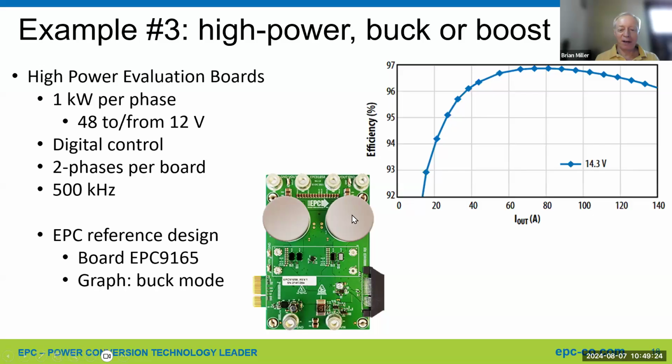But another point is the inductors. You might think, well, inductors are inductors, but there are some companies, one company is Würth Electronics. They make some inductors that are actually kind of polarized. So one is meant for the switching node, the other is meant for the output. The switch node is closer to the ground plane on the board, so there's less distance. So reducing EMI through the FETs, through good layout, but also through inductors, can help to keep all the loops small, to keep high-speed nodes as close to the board's ground plane as possible.